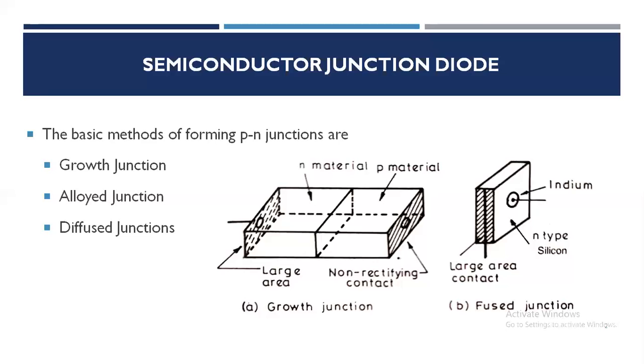The technique of growing an oriented single crystal layer on the substrate wafer is called epitaxial growth or epitaxy. A variety of methods are used to provide the appropriate atoms to the surface of the growing layer.